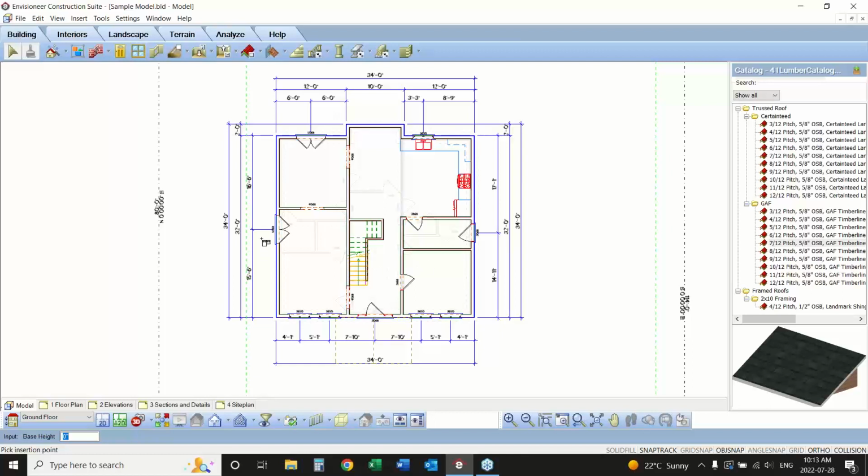You have to cross entirely through the wall. So if I want to dimension all the way through here, I can't start midway through this wall. I have to cross entirely through it for it to see it. So always go outside your building, left click, pull all the way through, left click. And as it crosses a wall, it will dimension to it. And you can see that it left off the dimension between the wall faces. So I'm not dimensioning that cavity between the 2 finishes of that wall because I ignored that interior wall dimension.